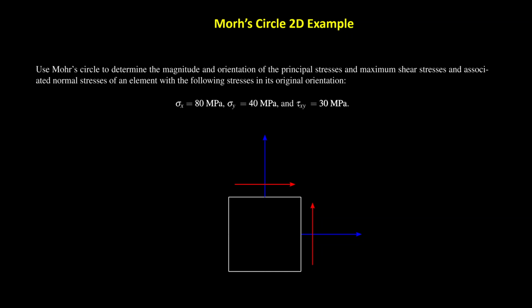These shear stresses are going to be the same because of the reciprocity of shear stresses, as we see in the 3D case. But which value corresponds to which? We have the x direction, which we have taken in all of our exercises as the horizontal axis, and then the y-axis, which we have been representing as the vertical axis.